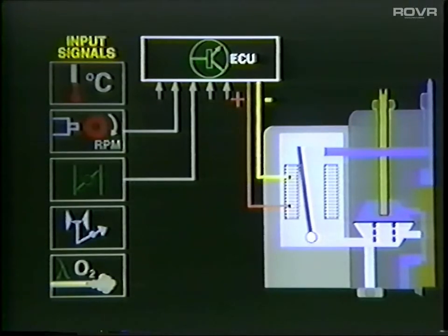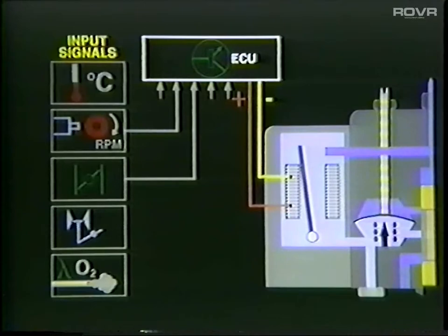This results in the leaf valve moving completely away from the inlet orifice. Full system pressure enters the lower chamber, deflecting the fuel distributor diaphragm to the maximum upward position. Fuel delivery to the engine is completely shut off while coasting.